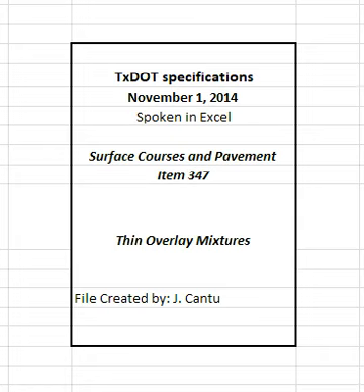Provide mineral filler, when used, that is sufficiently dry, free-flowing, and free from clumps and foreign matter as determined by the engineer, does not exceed 3% linear shrinkage when tested in accordance with TEX 107E, and meets the gradation requirements in Table 3. Table 3. Gradation requirements for mineral filler. Sieve size and percent passing by weight or volume. Sieve size number 8 with 100% passing. Sieve size number 200 with 55 to 100% passing.